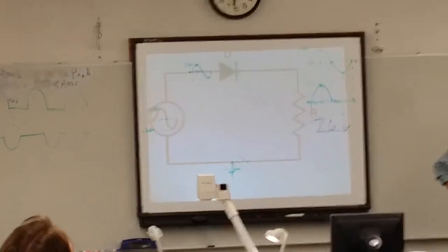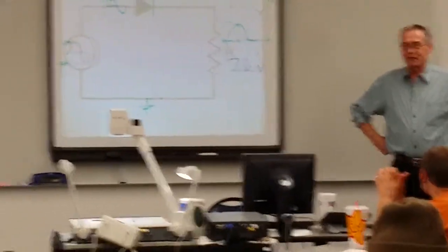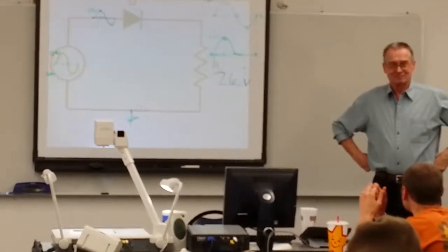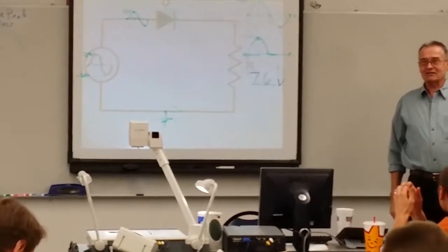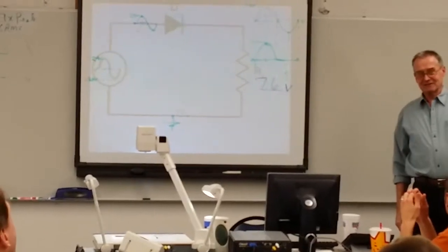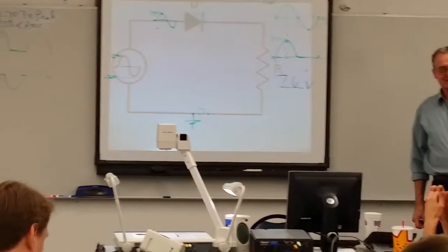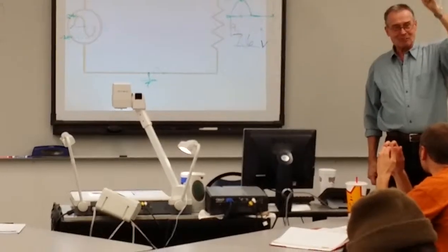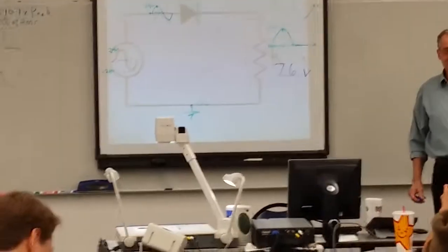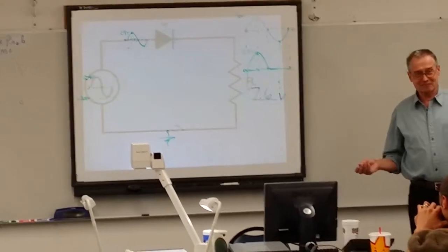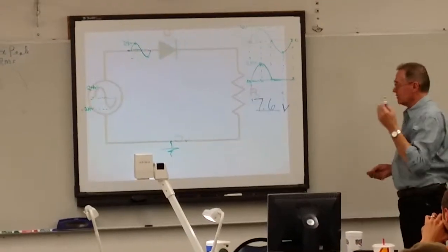And it will, because a dead battery is like a short. A dead battery is going to be about 10 ohms resistance. But as it charges up from 0, the resistance goes up. Instead of being low resistance, it goes to high resistance. And so it automatically limits the current, you see. Like its resistance automatically changes. And so it works great.